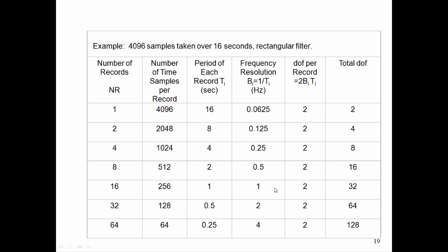So what's the correct answer for a given set of data? That depends. It depends on what the goals are, the objectives. If we're doing a shaker table test, and it's a broadband random test, a base input power spectral density to an avionics component, typically we would want our resolution to maybe be about 4 hertz, maybe a little higher, maybe a little lower, sometimes 5 hertz, maybe sometimes 10 hertz.